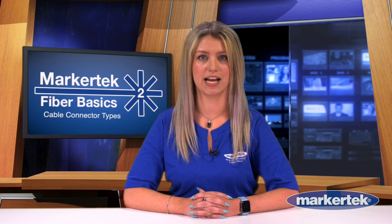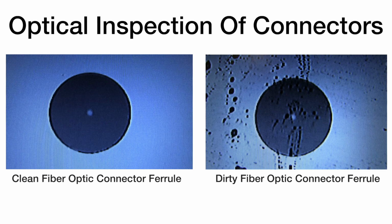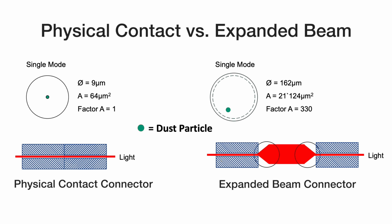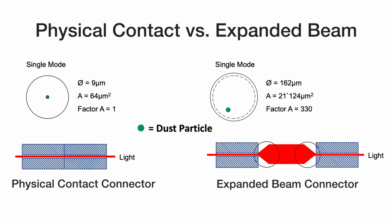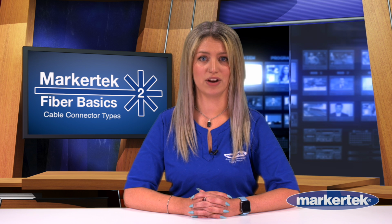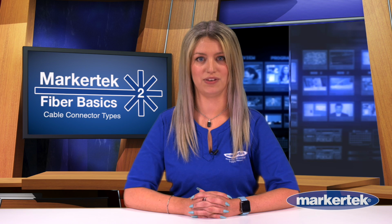One of the downfalls of all of the aforementioned physical contact connectors is that even the smallest amount of dirt can make your signal go dark, so fiber cleaning is an essential piece of system maintenance. Expanded beam systems excel in this area. They are contactless and use lenses to expand and collimate the light signal. The expanded beam can be as much as 150 times larger than the original fiber core. This makes the tolerance for dust and debris much greater, and they are easier to clean since you're not actually touching the fiber end face.